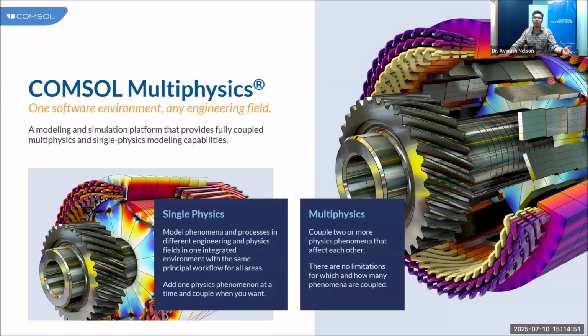There, the current flowing through the rotor conductors, which is used for making the magnetic field, will be very heavy. So the heat produced will be very heavy, leading to changes in the material properties. So that needs to be simulated in a simultaneous manner, like in every time step, what is going to be the effect of temperature on the current or current on the temperature, that we can do in multiphysics.